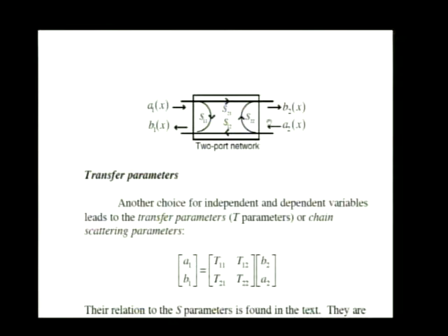In general, how would you figure out, in a general two-port network, how big a signal would be coming out of port 2? Well, I can think of two ways to have a signal come out of port 2. One thing that could happen is I could put a signal into port 1. And maybe that thing is an amplifier, and maybe it amplifies with this forward transmission coefficient, S21, to produce an amplified signal coming out of port 2. Right, that's a good way to get a B2 coming out of the other side. But that's not the only way.